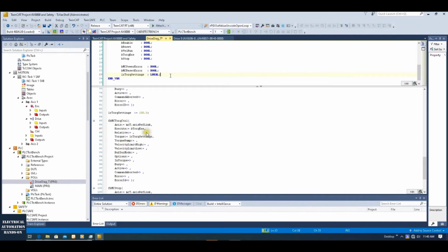I will show this case. If we switch the torque mode and the velocity mode back and forth, every time we switch back, we set a new value and a trigger, which is fine. However, if we only use the torque mode, and if we need to update the different set point for this torque setting here, we need to use 2 instances of torque control. I will show this case after. Just to mention here at first. So keep in mind, if you need to update this torque setting, you need 2 torque control here. This is a similar idea as the velocity function block, MC move velocity.